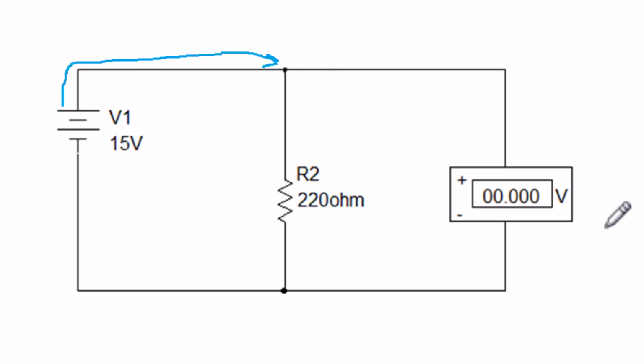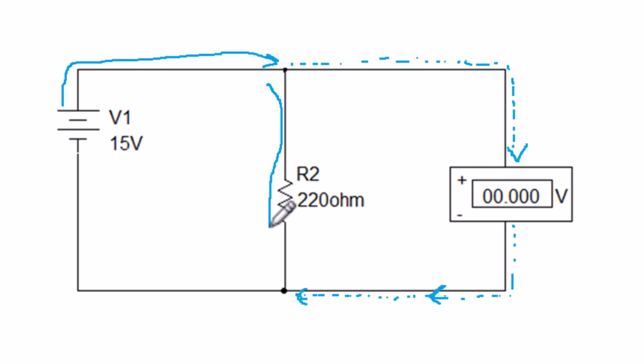The voltage drop of the meter is going to be the same as the voltage drop across the load because they're in parallel, but the currents are going to be different. And if you have a very large impedance in your meter, then it's going to impede the flow of current through that meter. So most of the current will flow through the load. When you have a meter that you're trying to measure accurately to a load, it is very helpful to have a very, very large impedance.